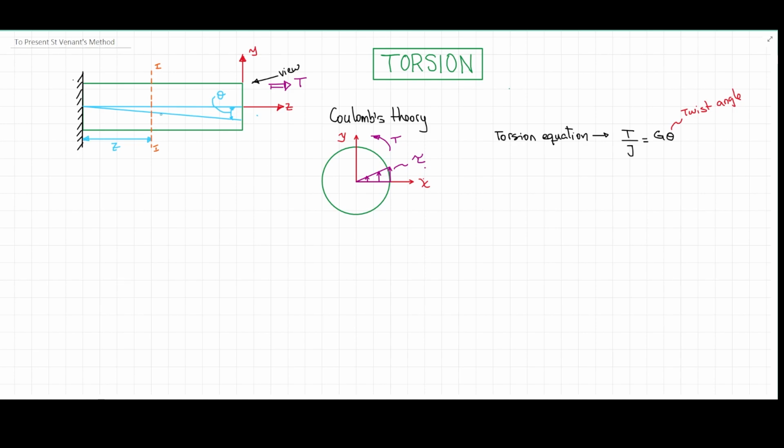So let me continue then and draw this non-symmetrical section. It would be something like this. I'm going to draw, again, a Cartesian coordinate system, and I'm going to draw it like this on purpose to let you know that it doesn't have to be in the center of that shape. Actually, shear centers of certain geometrical figures are outside of the physical bounds of the figure. So they are not found inside of the physical, or bounded, material. It might be outside of that.